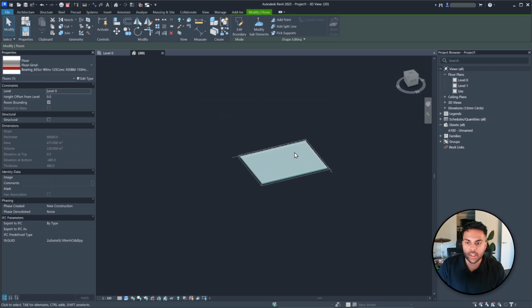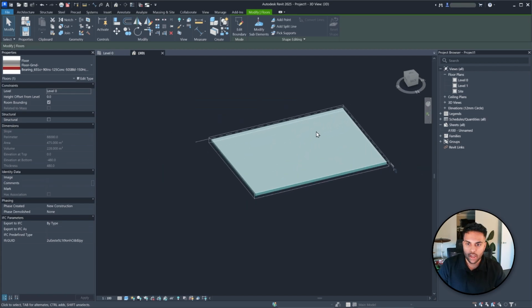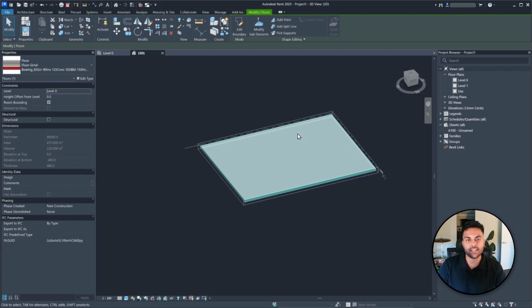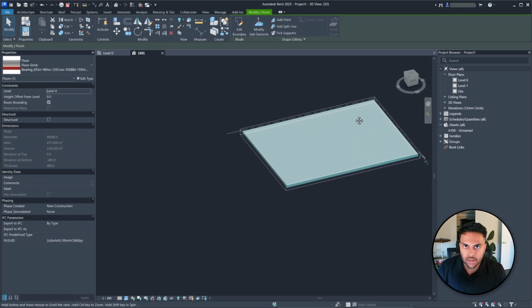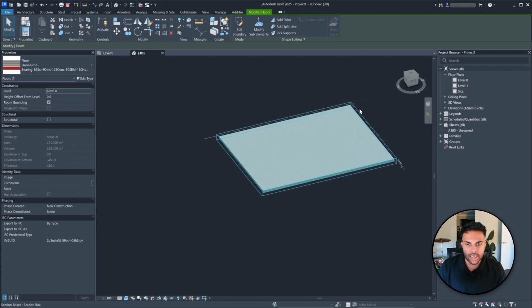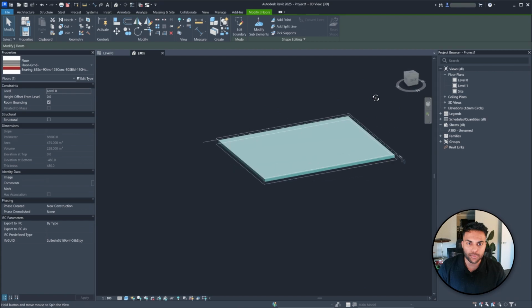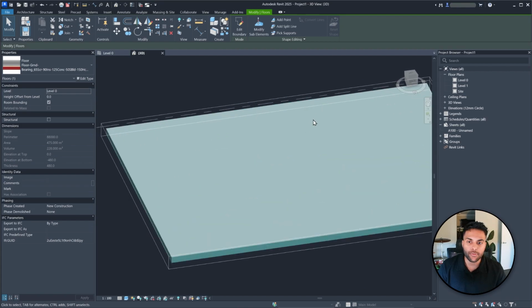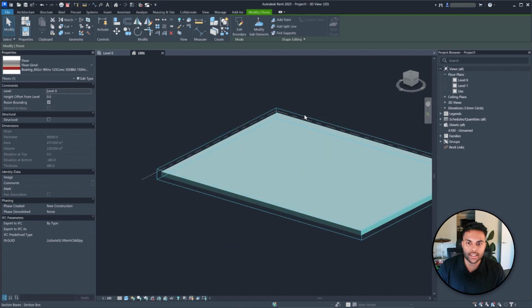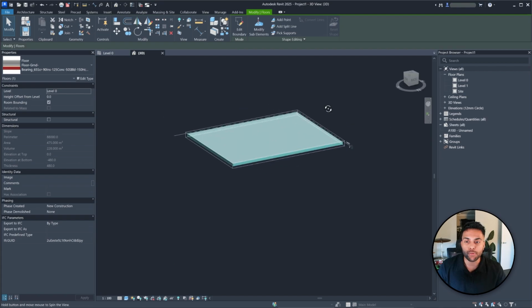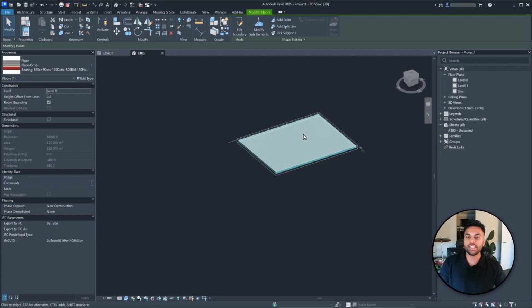So you can toggle from 2D to 3D. And in this 3D, you can zoom in and out using your mouse. You can pan just by clicking the center. So if you have your scroll wheel, if you select the scroll wheel, the center, you know how you can click it? You can actually move around. And if you hold the shift key, then you can start to rotate. Those are the three things you need to know, right? If you zoom in and out, you rotate around the thing, and you can pan, you can do anything in Revit. That's all you need to know.